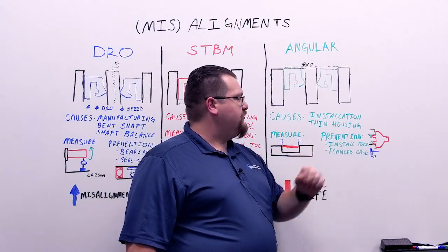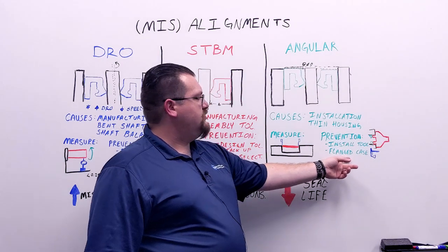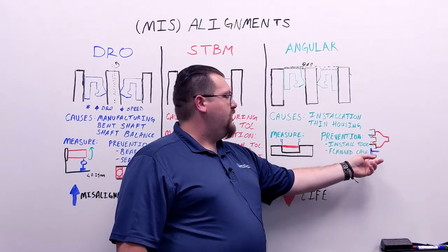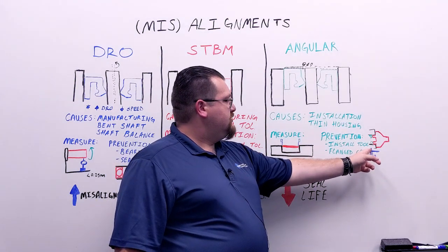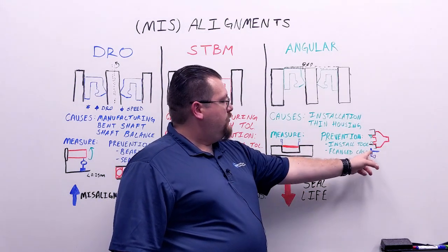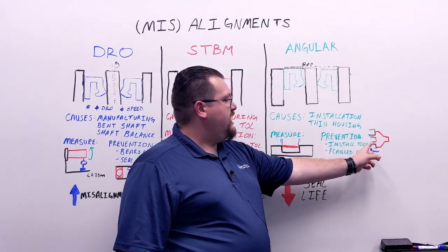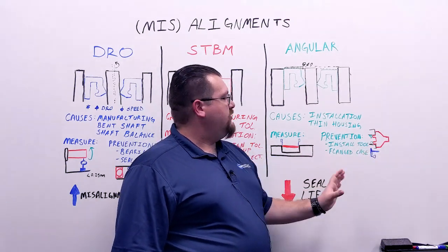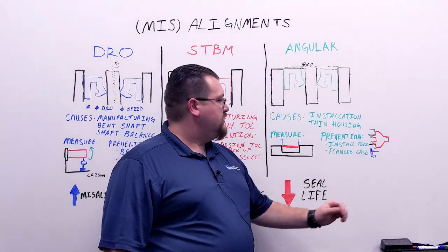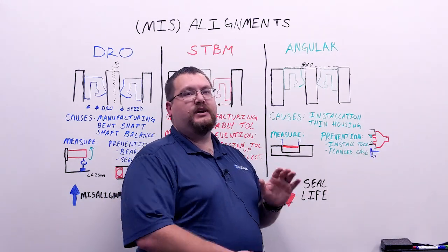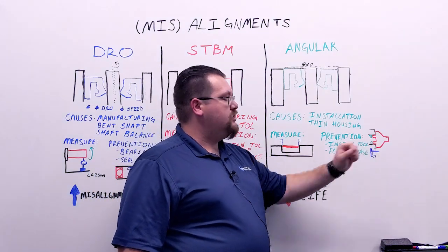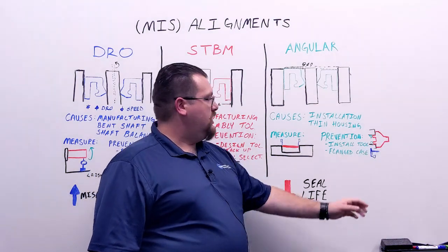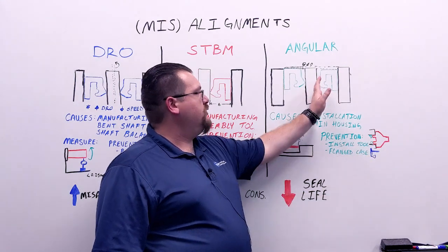If this isn't an option for you, then we can look into the seal itself and we can use a flanged case design. In this example, there's an extrusion on the case. It points outwards, and when you install this flush, the seal case will hit the face of the housing, and therefore you know that it's also perpendicular with the shaft.